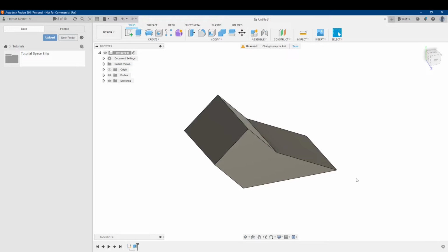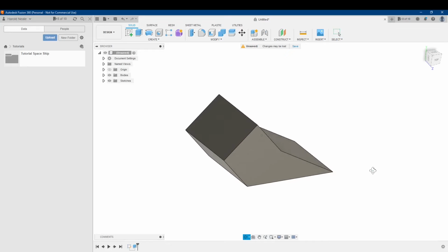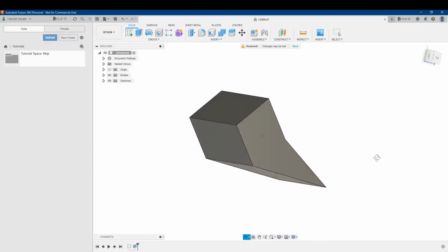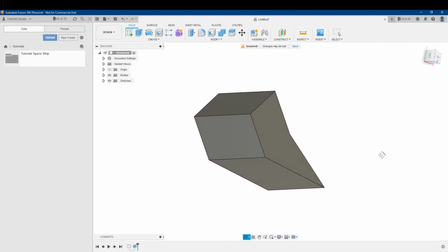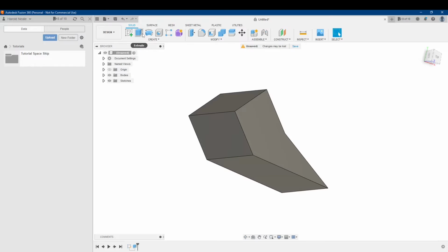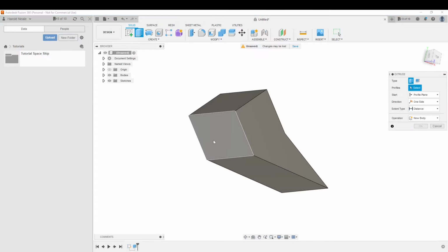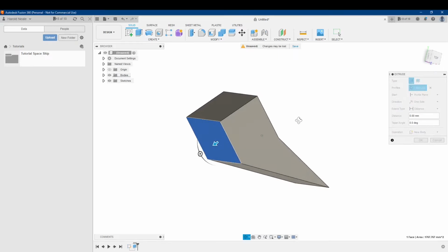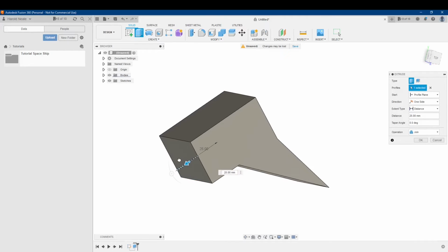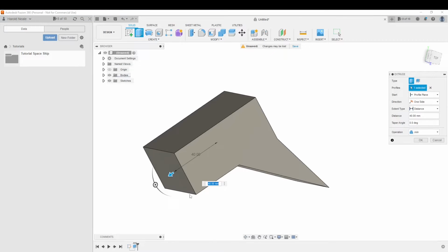Now that you have a 3D model, you can extrude other things out of it. You don't necessarily have to create a sketch. So let's try extruding from one of these faces. Extrude from this face. So profile, this face counts as a profile, so we click on that, and we can stretch it out just like that. Now you probably noticed this I guess circular slider here.